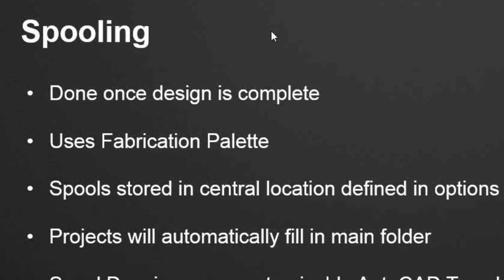So you can start spooling before your design is complete. You just need to be aware that you shouldn't copy any objects once they are spooled. Once that happens, it becomes difficult to remove that spooling information from your object.